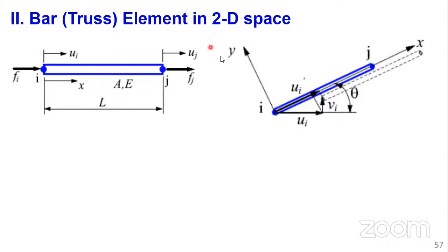Global coordinate is the one you are used to, horizontal X, vertical Y. And we are saying the notation uses capital letters to denote the global coordinate system. So each one of the elements is oriented in a different direction, and we are trying to transform them from this axis, the small x, the small y, to the global coordinate system.